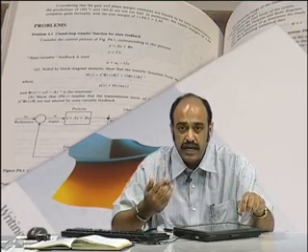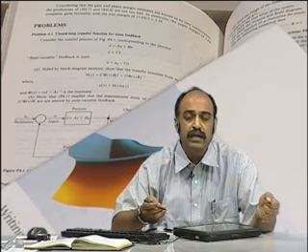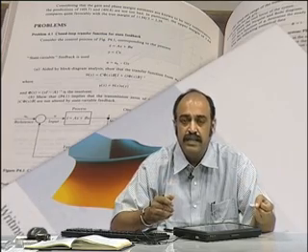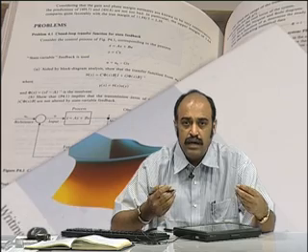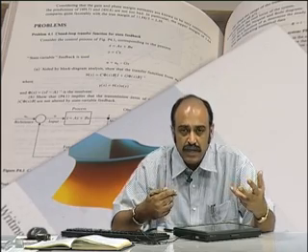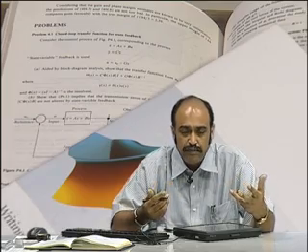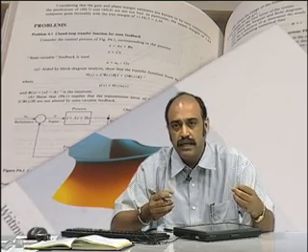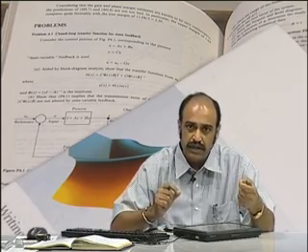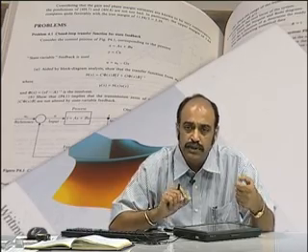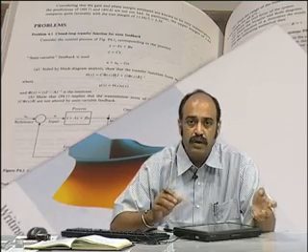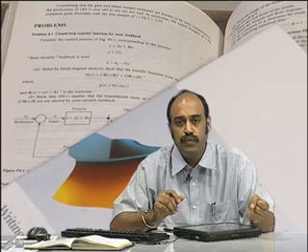The variation of the gain with frequency is not very evident in the time domain. The bandwidth is not so very evident in the time domain. The pattern of the poles which will give you oscillation or which will give you that amount of damping is much more easily understandable looking at the pole-zero plot. In fact, in the pole-zero plot you can position, this should be the damping, this should be the position of my poles, and work back and then evaluate what should be the value of LCs in the circuit, and that will be useful for design.